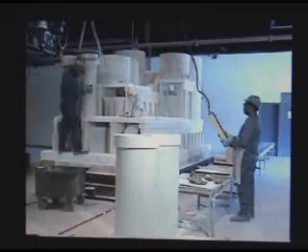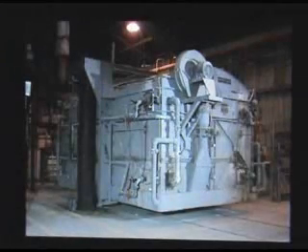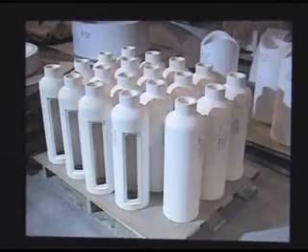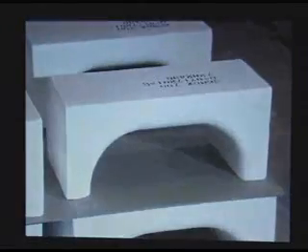Expertly constructed hard plaster molds are filled with thixotropic ceramic mix, which becomes more fluid when energy is applied. Then vibrated so that the material takes the exact shape of the mold cavity. The castings are then dried and fired using a long high-temperature cycle that produces strong shapes resistant to chemical attack and crack. Each finished piece is individually inspected before shipping.